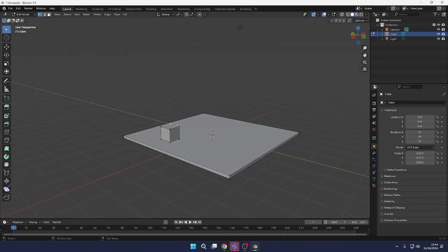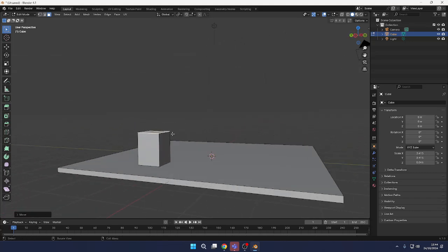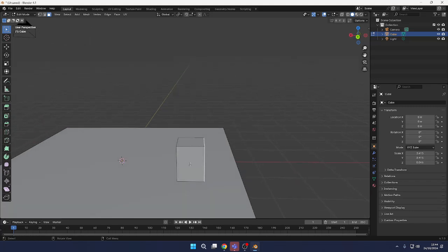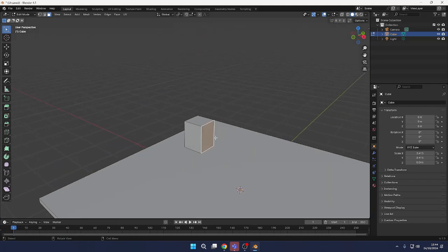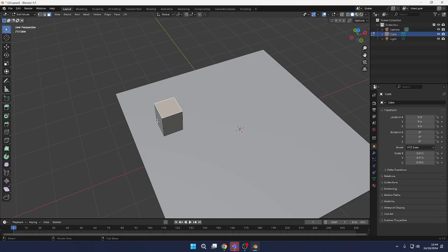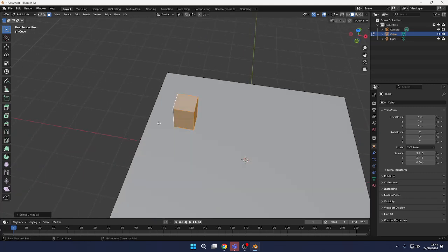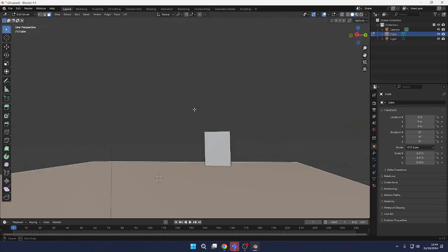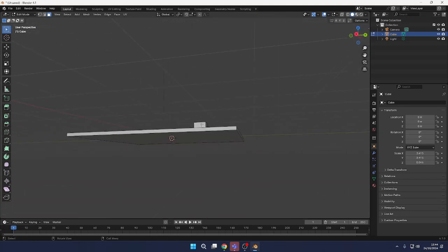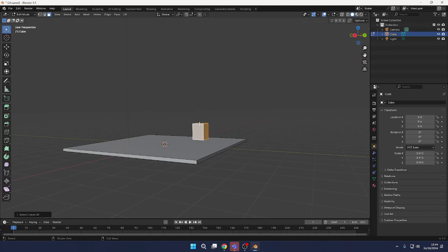Last time we said if we just want to select individual vertices, this is fine. But I want to select faces, or press 3 on the keyboard. There we go, GZ. And it's really useful to be able to select all of the linked vertices at once. So a new keyboard shortcut that you might want to add into your list is Control and L. That lets you select all the linked vertices. Look, these are separate objects. There's that, Control L, get all of those. Or this, Control L, get all of those. So let's get that, Control L.